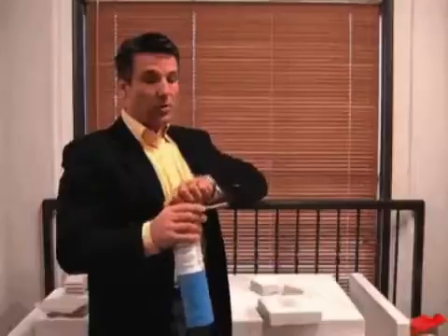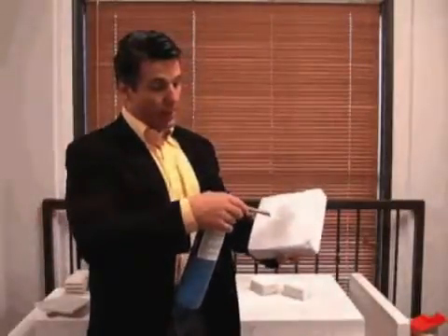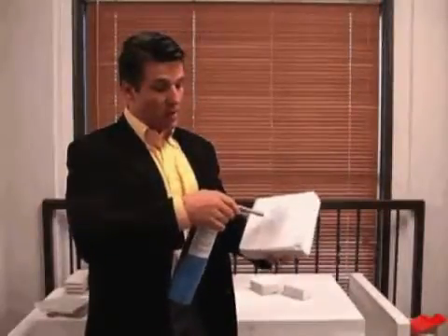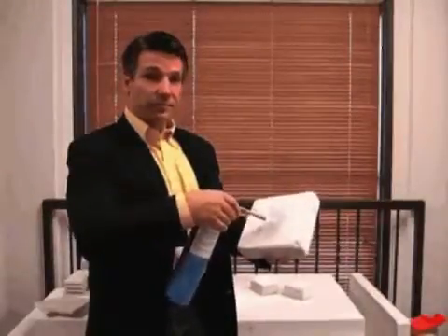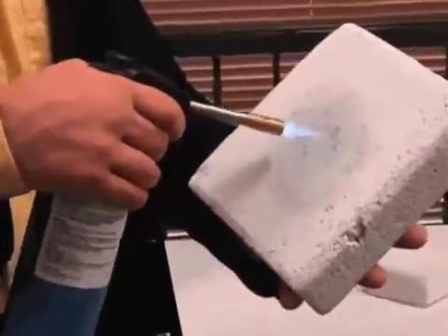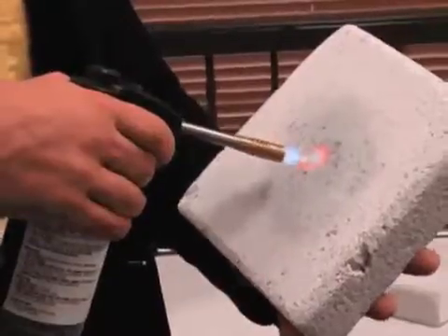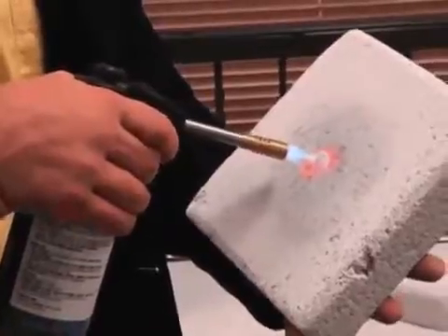So I have a regular propane torch here, which can develop approximately 1995 degrees. So I will use it, as you can see here, and hold it right onto the AAC, which is only 2 inches thick. So right now I'm coming close to 1000 degrees, 1500 degrees. And now you can see the red spot already. So now I'm close to 1995 degrees. It's where steel basically starts to deform slowly.